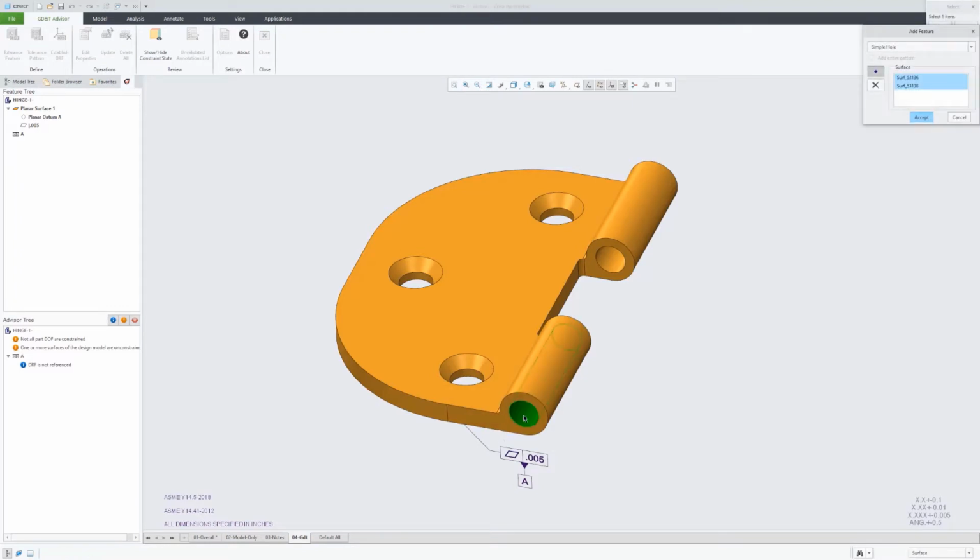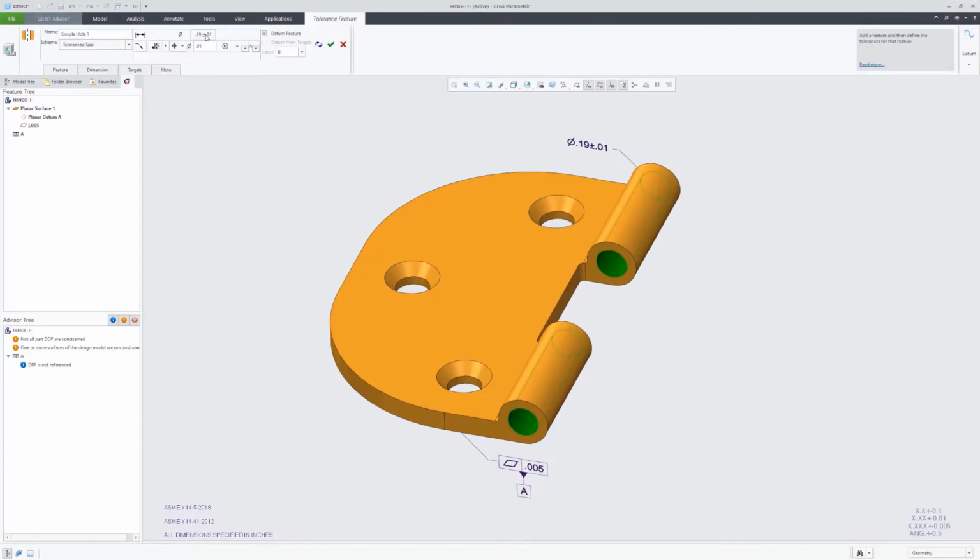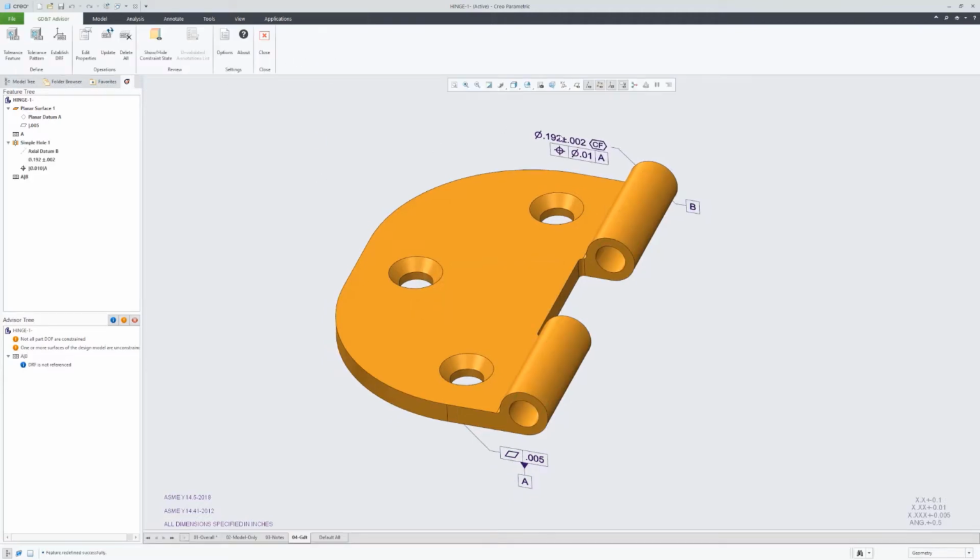Next, if we move on to datum feature B, we split that hole into 2 surface regions and collected that. And the reason we split that into 2 regions was so that we could add, as you'll see here in a second, the continuous feature modifier. So that is a feature of size. Here we're going to add that continuous feature modifier as well as the true position tolerance to qualify that.